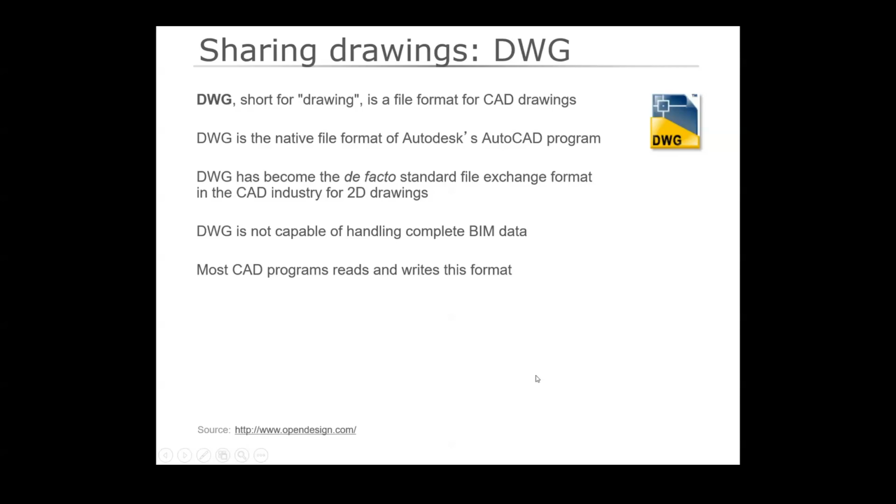Is it possible to do 3D DWG? Yeah. I only really discovered it not long ago myself, how to do it. It's just a simple save as DWG. It doesn't say 3D, just save as DWG. So you have to do it floor by floor in 3D? No, just go to your 3D model and save, and it will save it as a full 3D model, so whoever's using the software at the other end can do that.